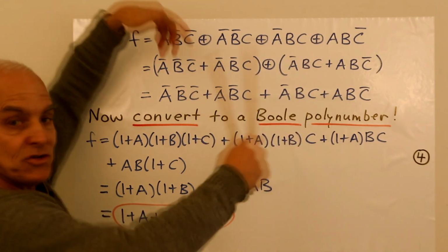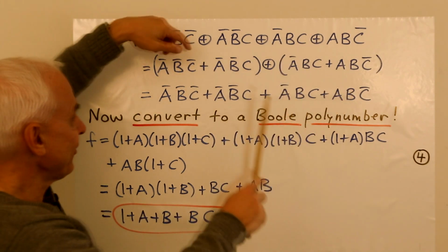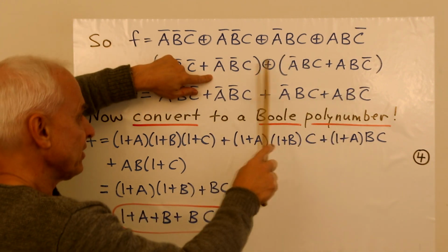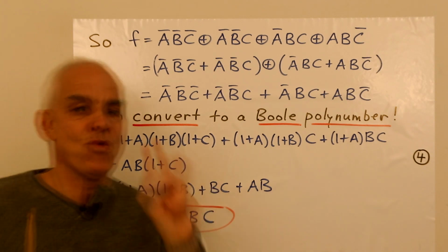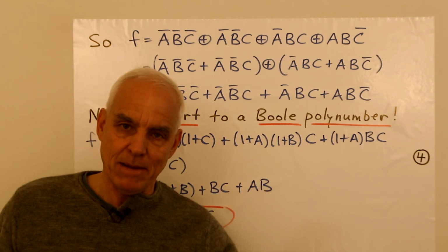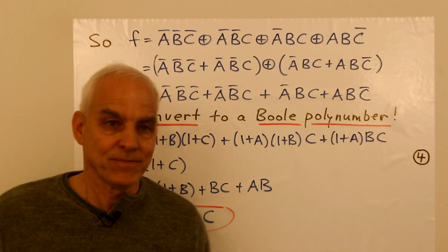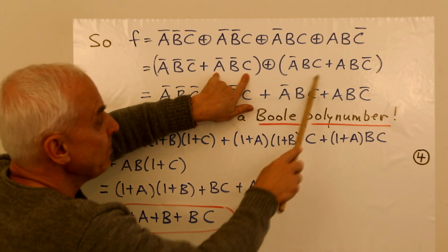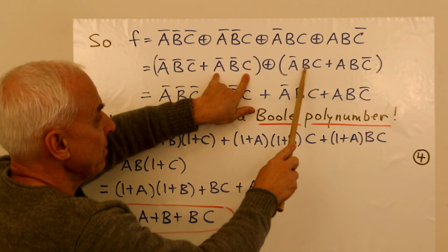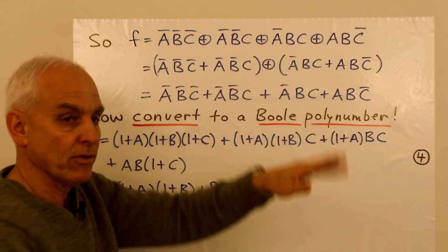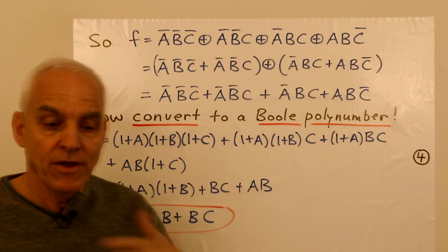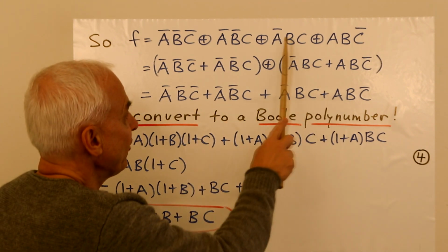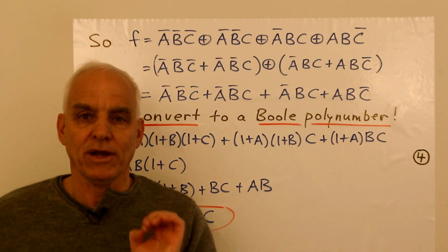Well, the product is, by the distributive law, a lot of little products. So we have to take the product of this times this, plus the product of this times this, plus the product of this times this, plus the product of this times this. But each one of those products is subjected to exactly the same phenomena that we've just talked about. Take any one here and any one here. There'll be at least one input where they differ. In this case, B. B here, B bar here. So the product of these two is 0. And that happens for all of these four products. So all of those products are 0. So we do indeed get to replace the circle sums with just ordinary sums.